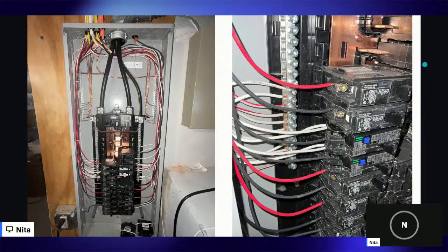So your panel board, when you remove that door, on the door of the panel, it should be labeled. All of your circuits should be labeled. So it should say stove, this, that. All of your circuits should be labeled on the description. So it will list your manufacturer, the model, your max amps, the breaker sizes, all of that kind of information that must be there. That is also a reportable defect if not.